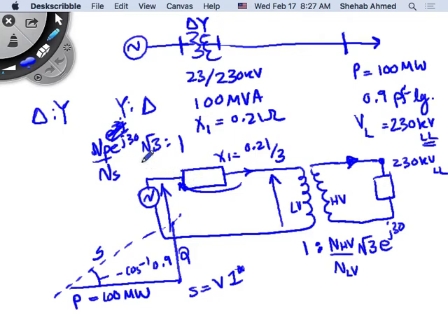If I would like to bring these on this other side, I just want to change the turns ratio. I mean, the turns ratio will remain the same. The ratio will remain the same. I just want to, instead of writing 1 to 2 as the transformer ratio, I write what? 1/2 to 1. Right? This is still half of this. This is double this. It doesn't matter. If you take these quantities on this side, divide them by the quantities on the primary side, you will put 1 here. Right? So I will do the same.